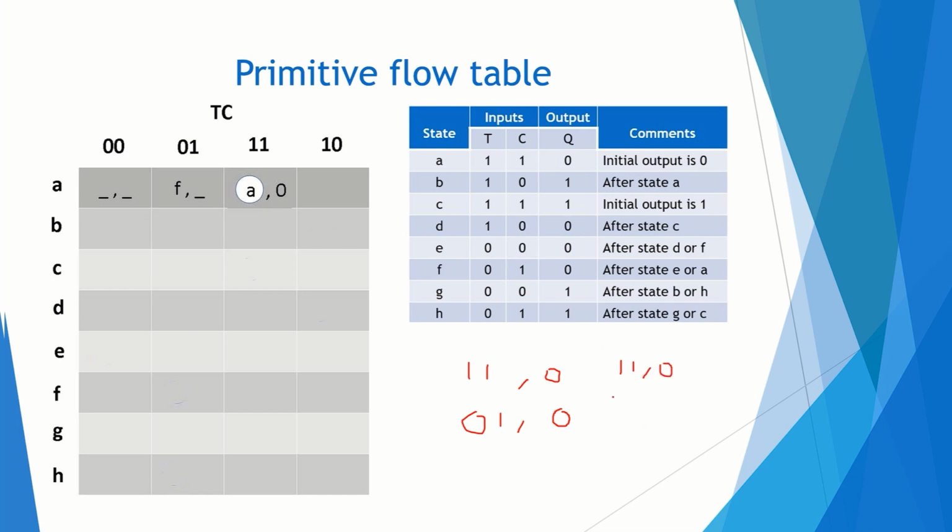It goes to 1 0. So C is changing from 1 to 0. So there will be a change in that Q output, and T is equal to 1. So it is complemented. So 1 0 1. You can see where is 1 0 1. It is B. So it is B dash. Again go from B, 1 0 1 0, and it is B1. Okay. And the unallowed transition is 0 1. You cannot change from 1 0 to 0 1.